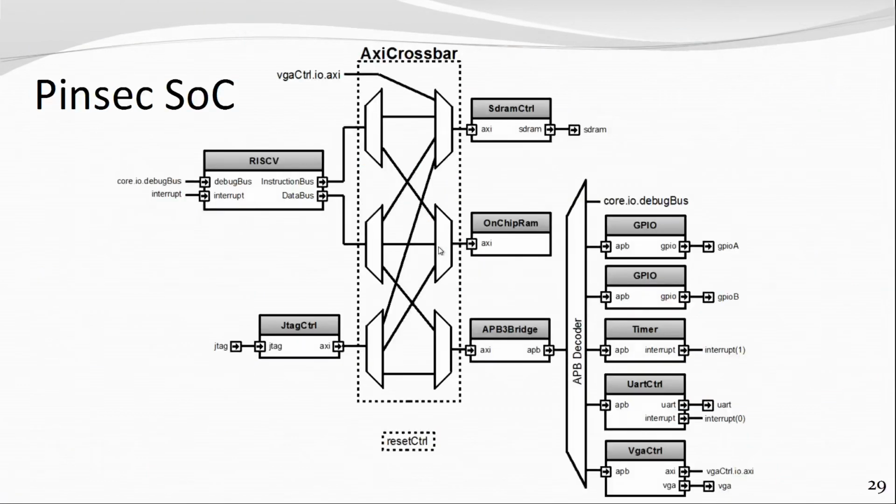Then, yeah, it is a project which was made with SpinalHDL, which is kind of a little microcontroller with a RISC-V CPU, with instruction cache, with multiplication and division extensions, and these kinds of things, with a JTAG tap to debug it by using breakpoints and things like that. There is an SDRAM controller for external memory. There is on-chip RAM. There is an AXI4 crossbar to connect all those guys together with a good bandwidth. There is an APB3 bridge to go to peripherals, which are a GPIO, timer, UART, or VGA controller.